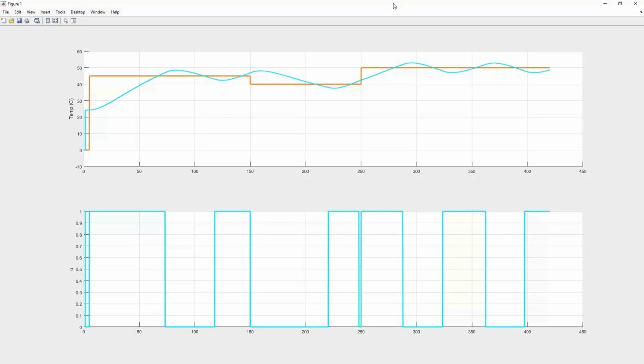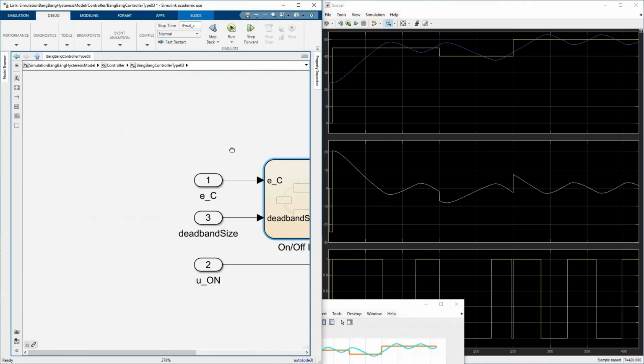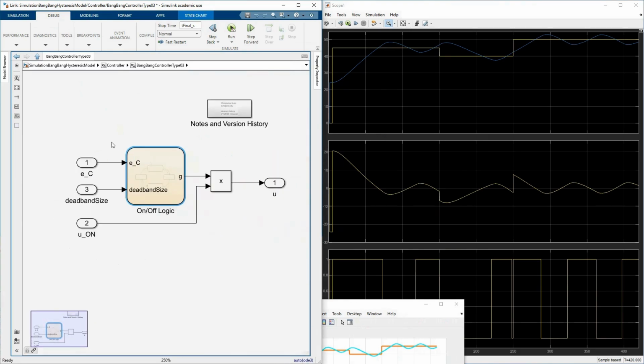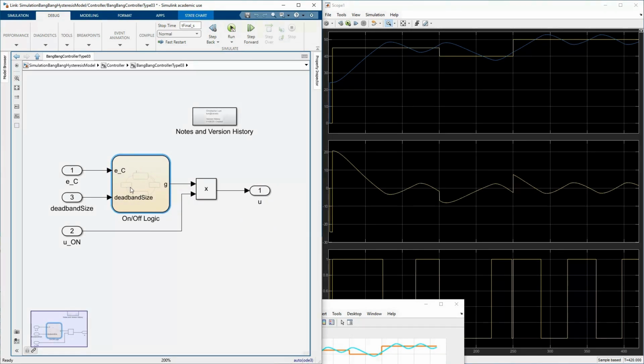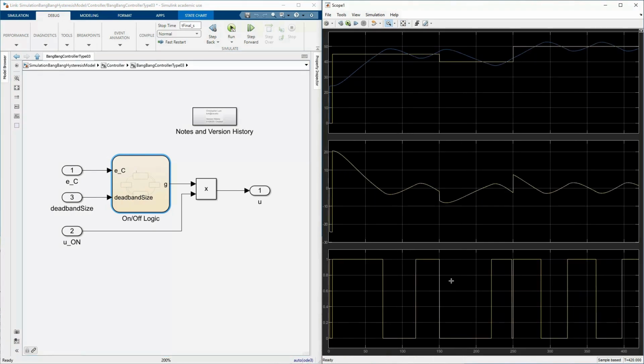Now, you might be asking yourself, okay, fine, if this or the Stateflow, both of these things are equivalent, right? It's both implementing this algorithm of having a bang-bang controller with a hysteresis deadband. I obviously like this better, so why don't we go with this for the rest of the discussion? But I'm sure you're asking yourself, okay, fine, what's the price we're paying for this? Obviously, this is great because it eliminates chatter, but there's no free lunch. You're paying something for this, right? And what you're actually paying is a little bit of a hit in performance if all we care about is looking at tracking.